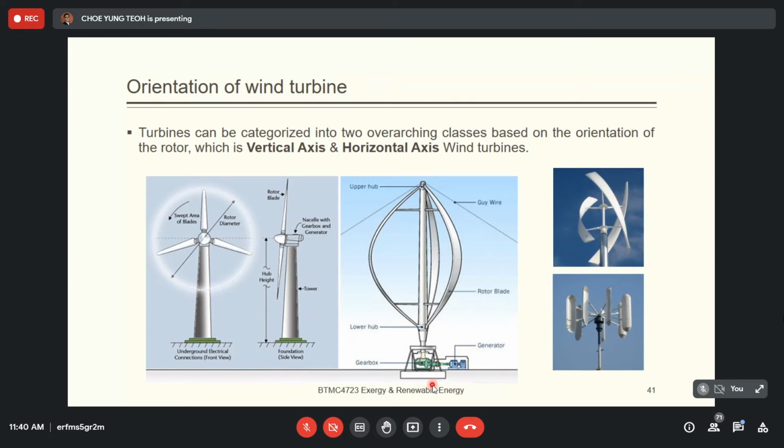First, you install the blade on the ground. Normally, why do we want to install the blade at a very high location? Because we do not want anything to block the blade. So if you build the turbine close to the ground, you will have lower or poorer wind speed. This is the first disadvantage, but it's not the main disadvantage. The second disadvantage is about the centrifugal force on the blade.